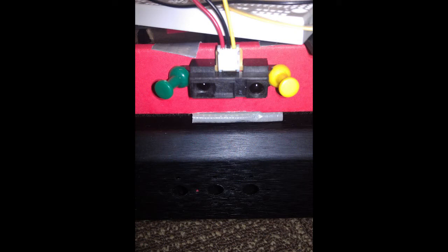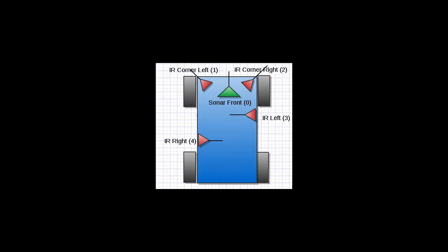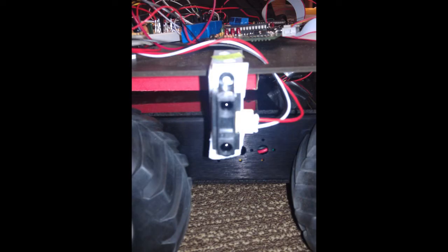The bulk of my visible work was the mounting and data acquisition of the infrared sensors. We chose infrared because we knew we weren't operating in wide open spaces where sonar would be king. Originally, we planned to mount the sensors in the center of the rover facing outward. By doing this, we would mitigate the minimum rated distance of each sensor. This ended up not being feasible, however, because the bricks used to construct the course were too low, which meant that we had to mount the sensors on the outside of the rover.